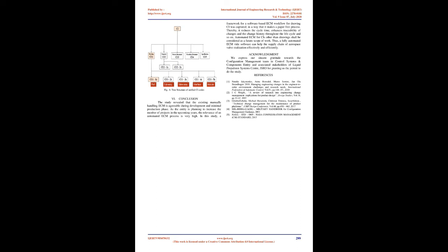Engineering changes are the changes that have functional impact on other supply chain phases. This can be of dimensional changes, changes in geometrical tolerances, material changes, surface treatment, spring specification, and so on. Whereas, ad hoc changes are the changes which do not have functional impact on any of the supply chain stages. The major categorized ad hoc changes are addition, removal, or modification in tabular details, engravings and so on.